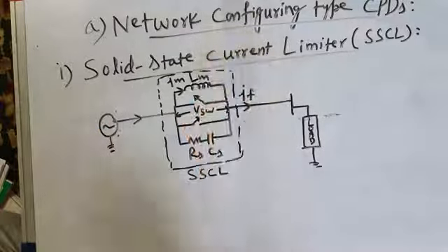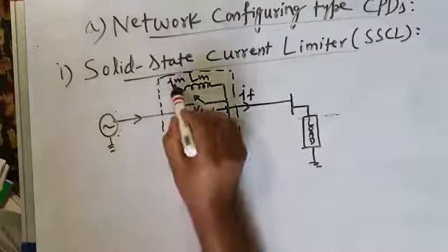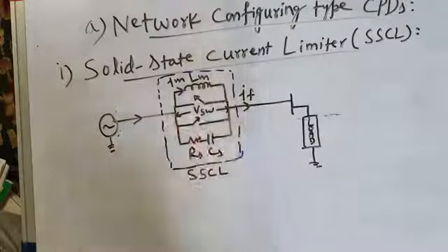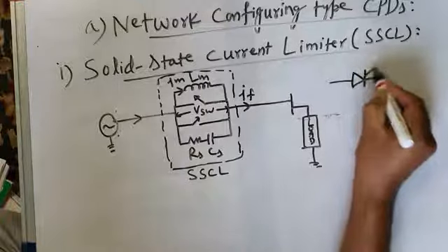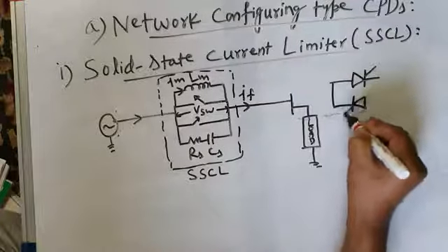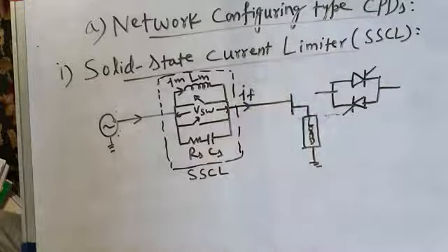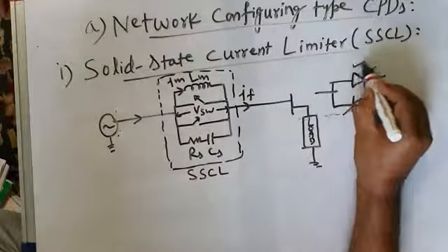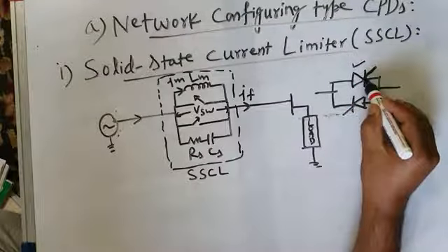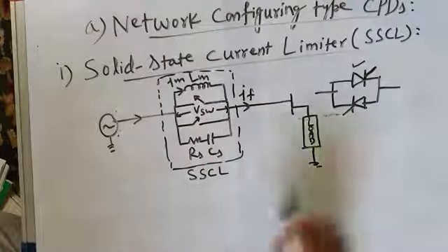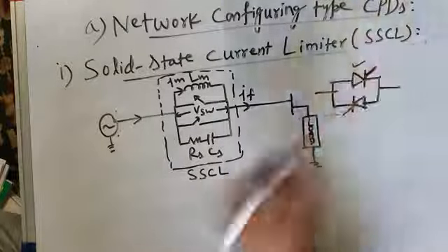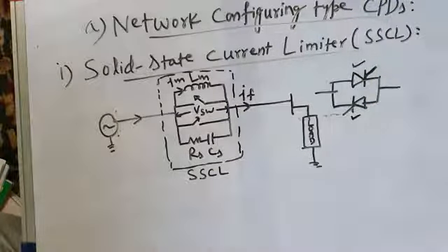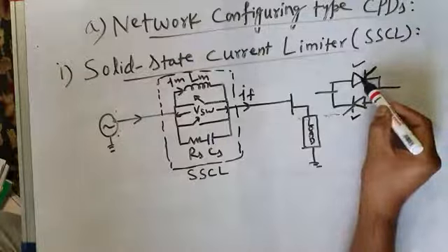Now what is this LM? LM is the current limiting reactor, and the current flowing through this current limiting reactor is IM. The feeder current is IF. Now as far as these switches are concerned, they may be simple thyristors, SCRs, connected in anti-parallel, I mean this pair of switches. When firing pulse is issued to this thyristor SCR, it conducts current in this direction. And at that time, the other switch is in the off state because it is reverse biased by the voltage drop across this switch. And when this switch is fired, current flows in this direction, and at that time the first switch turns off.